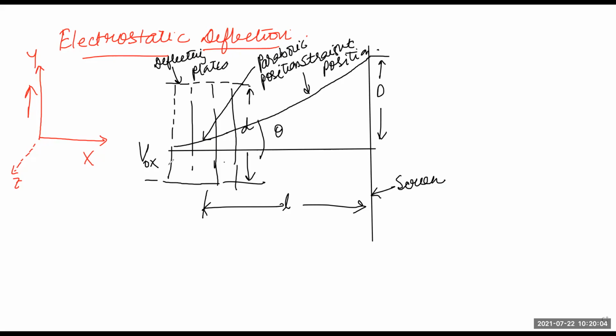So from this picture, I want to tell you the notations that are important here. The first notation is EA. EA is the voltage of the pre-accelerating anode, which I told you. This voltage we require in writing a formula. We have a formula here. Accelerating anode. And where is the accelerating anode present? In the electron gun, right? Which I told you. Electron gun is a combination of the pre-accelerating anode and the focusing anode.